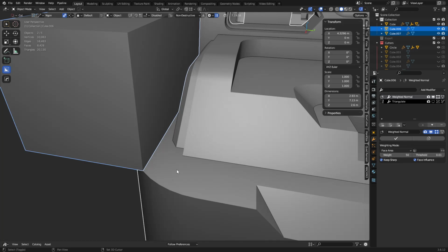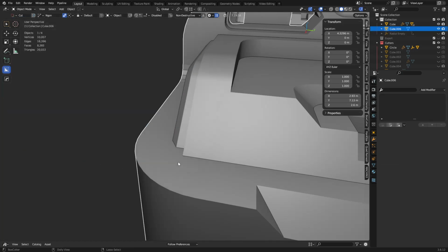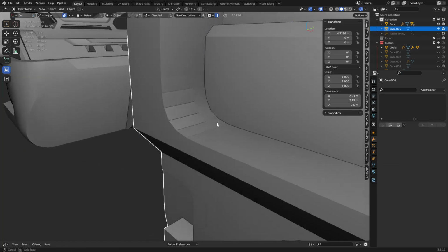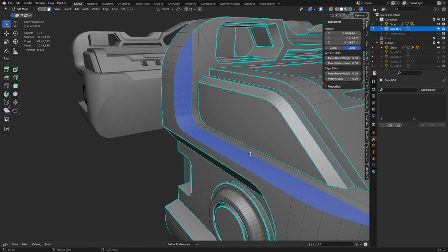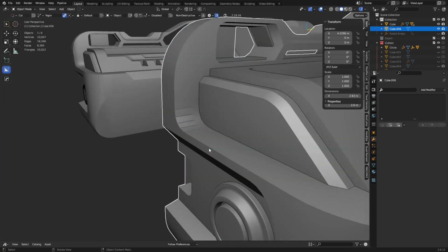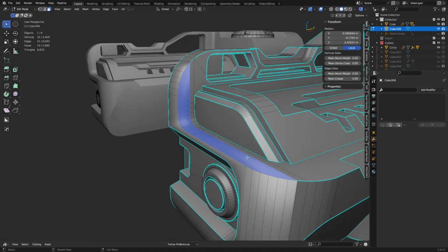Alt-N, recalculate it outside. I'm going to do a destructive Boolean subtraction. So I can chisel that all away like that. Using Bool Tools, Control-Shift-B. That's the Bool Tools menu. I used Auto Boolean Difference, so it's a destructive Boolean. Shade it Auto Smooth again, see what happens.